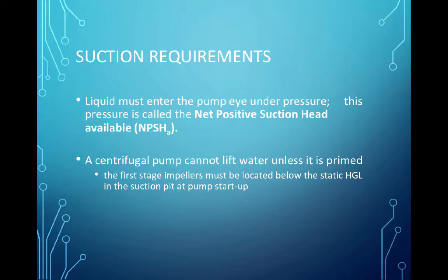That pressure is called the net positive suction head available. That's what's given to it by the system. And the pump manufacturer provides a value called net positive suction head required. And so the available has to be bigger than the required or the pump won't operate correctly.